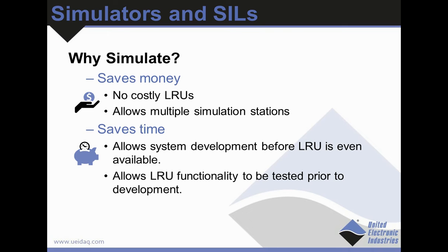In the SIL arena, you can simulate and save money because you don't have to use costly LRUs. The LRUs in the real aircraft are certified to DO 160, 178, 254, or sometimes mil-spec 810, 461, and these are very expensive devices. The simulated device doesn't have to be anywhere near as expensive.